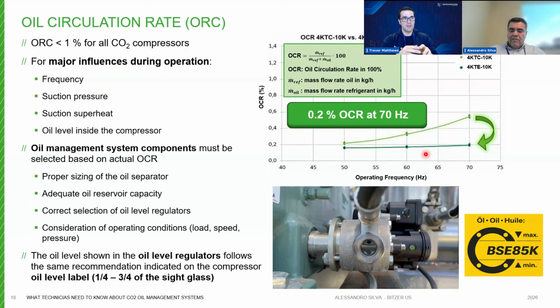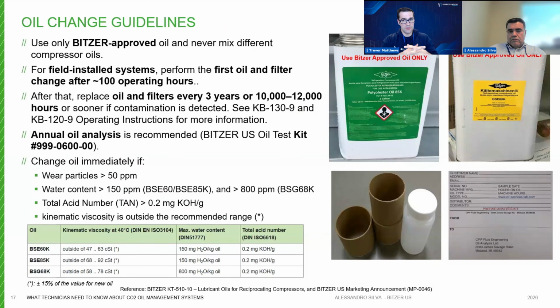Yeah, because this is one of the things too. We're dealing with higher pressure, higher mass flows, as well as that oil being very miscible, like that last slide you showed, very miscible with CO2 versus other refrigerants. So this is something you've got to be very aware of, because the temperature coming back to that compressor or leaving the compressor is going to affect how that oil is moving through the system.